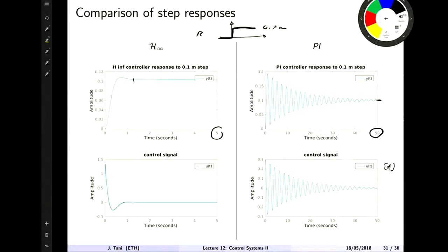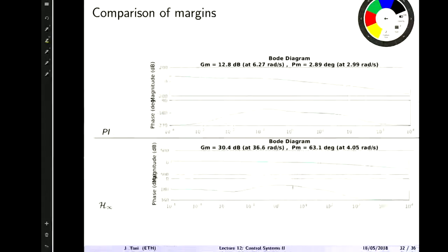Questions here? Yeah. It's small on the right side, yes, true. So this is why I said we go a bit higher here, but not too high, right? If you design this in MATLAB, you play around with it, then you can also get solutions which converge much quicker, so in 0.01 seconds, but then your current will go up to a few thousand ampere, which is probably not what you want, because you then don't have a servo motor anymore afterwards.